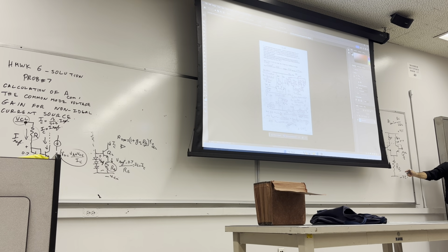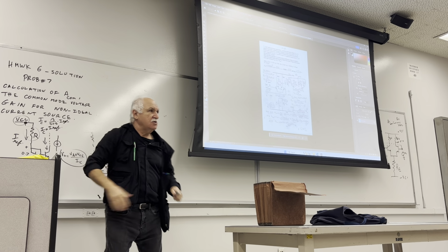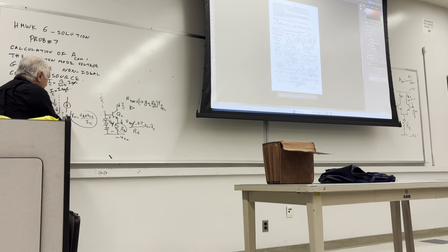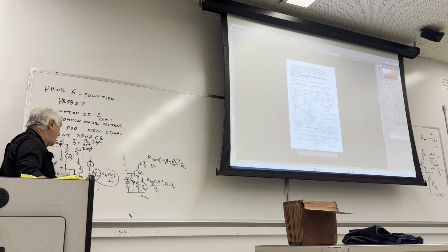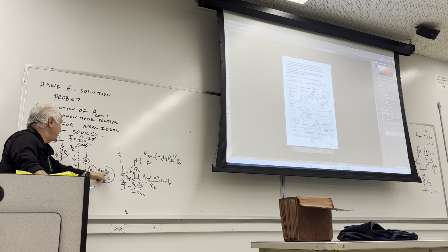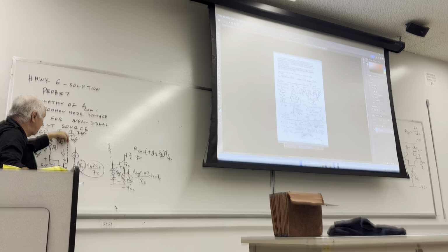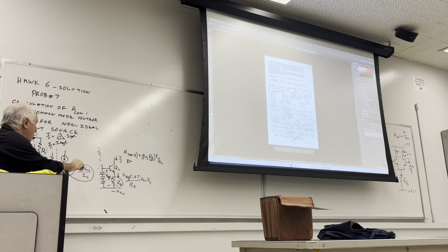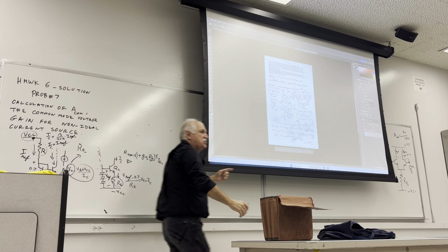If you had a current source, one of those mirror image current sources with its DC current and everything, after you're done with the biasing, you want to know what is the CMRR, you will go check out RO of that transistor. If this transistor was a regular one and the VA was given, and you know what is the VCE, and you know what is the I that it is sourcing, you could easily calculate the RO. That RO would replace the RE. Same formula.